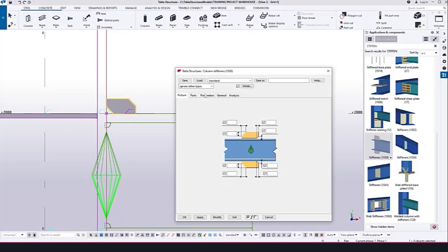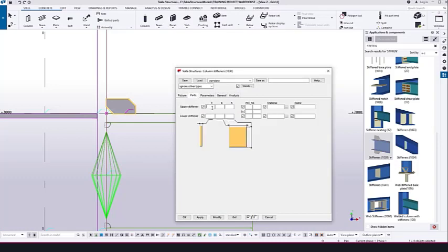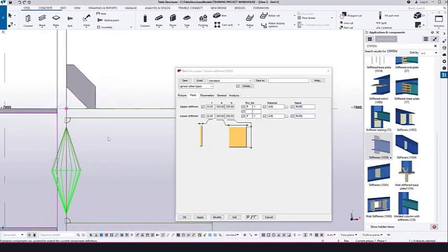We can customize this one how we require. Just make the thickness here, and I just make the size 300, and here also 300. What is the height, I just make it 200, and here also 200. Then the prefix and start number, material, depends on your project material, you can make it. And this is a plate, so I just make it here. Just copy this one, Control C and Control V. Then if you modify, here it is fixed like this.